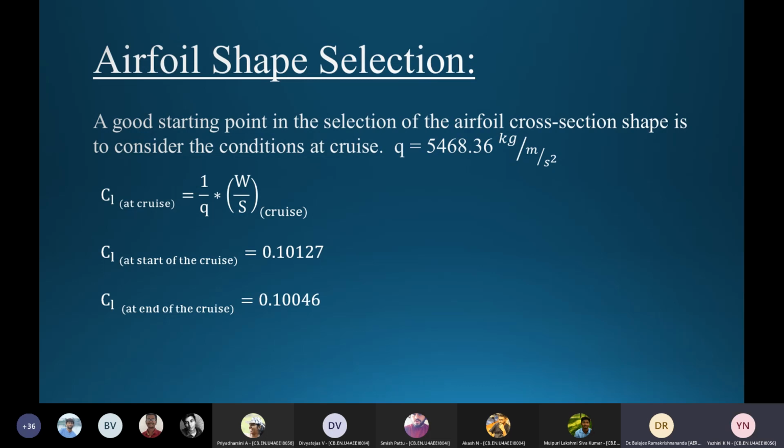Only then the W and this will actually, oh, W are you using in kg, is it? W by S in kg per meter square. Yes, sir. Ah, okay. In that case, you are right. But usually you take W in Newton, because when you say T by W, you'll make a mistake if you take W in kg.